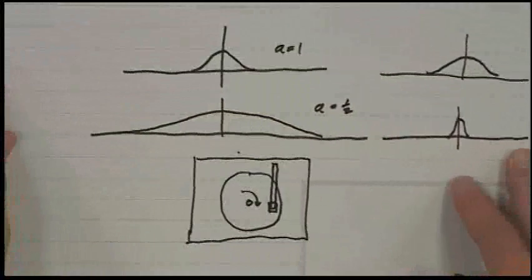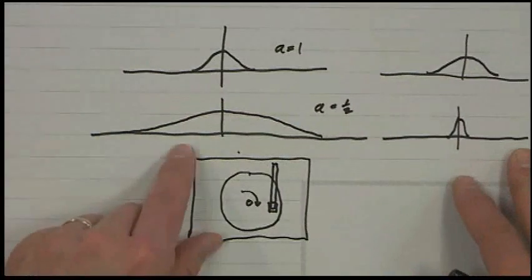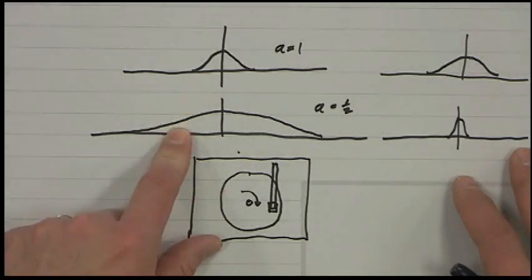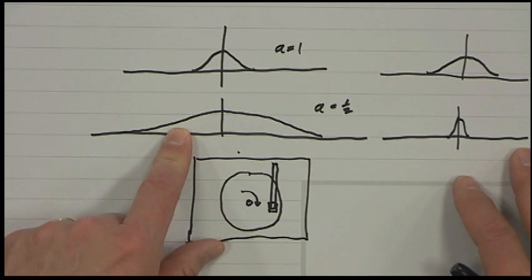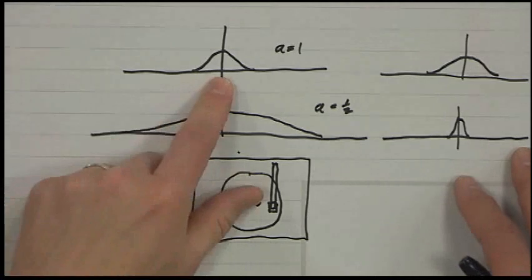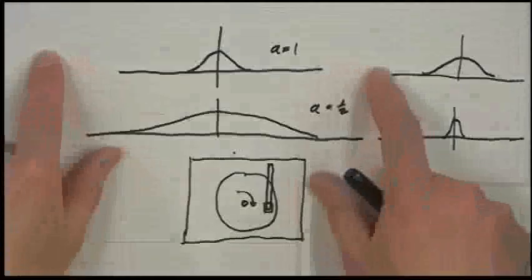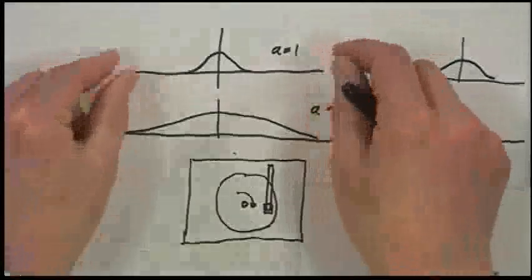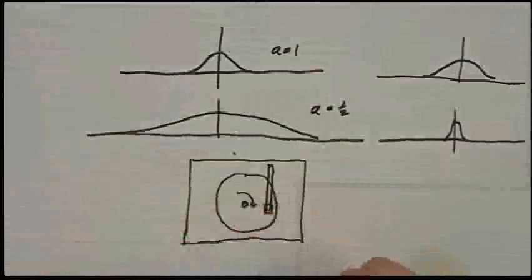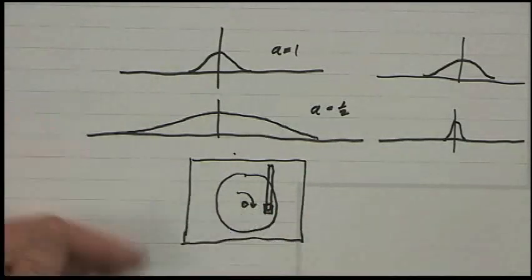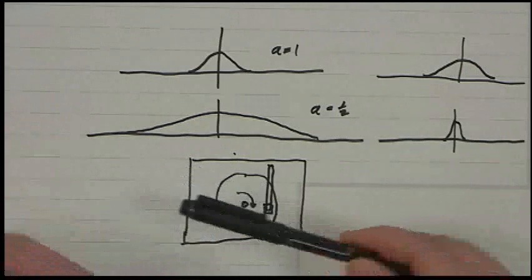The other thing that's interesting about the scaling property is that it has no direct analog in discrete time. So I'm sort of jumping ahead here, but if you sample a signal, and you stretch it, the samples don't fall in the right spots anymore, right? So when you stretch it, you've got a problem. It's like, have you ever played the game of musical chairs, where you have like n plus 1 people, but you only have n chairs, and they play music, and you walk around, and then when the music stops, you have to sit down.